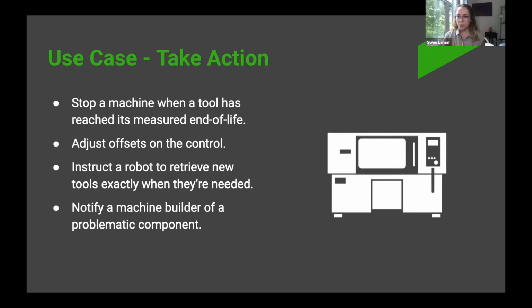Okay, so here's another one. Can an edge device be specific to a machine, or can one handle multiple machines at the same time? Yes. We have customers that set these up in a number of different ways. For example, a customer might have a number of machines that are on a local area network, and we'll use one edge device for that. But then they have one machine that happens to be cast off in the far end where their Ethernet hasn't arrived yet, and they can use a secondary edge device just for that one machine, connect it to their shop network over Wi-Fi or out to the internet via cellular, and be able to capture data from that machine just the same. Oh, cool.